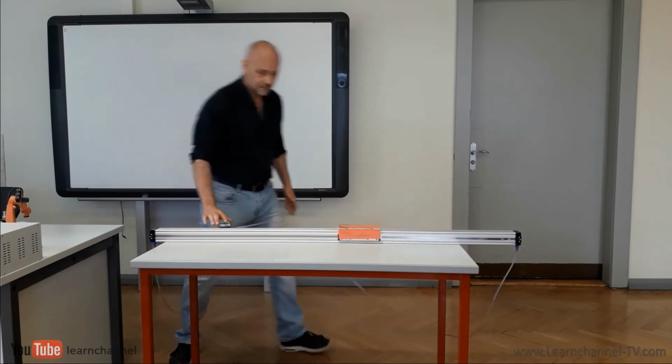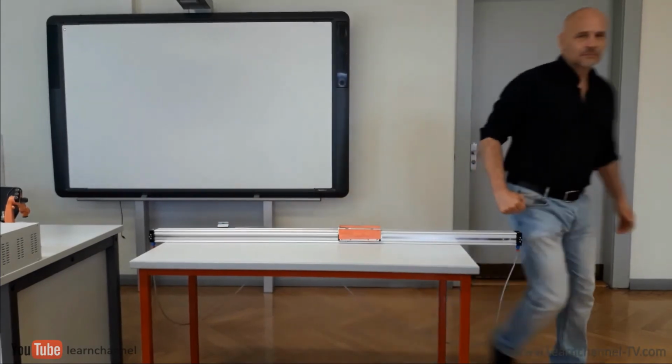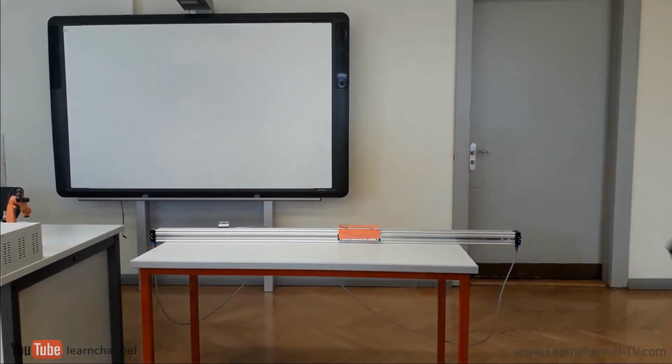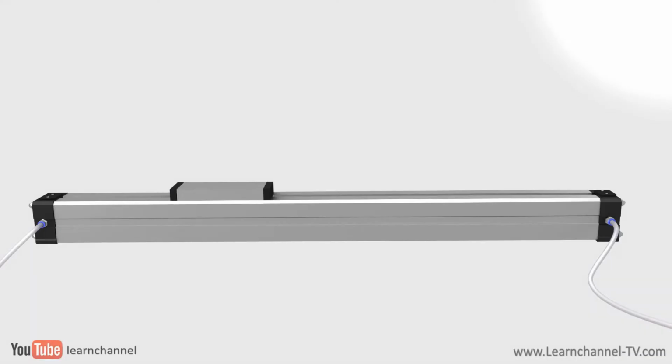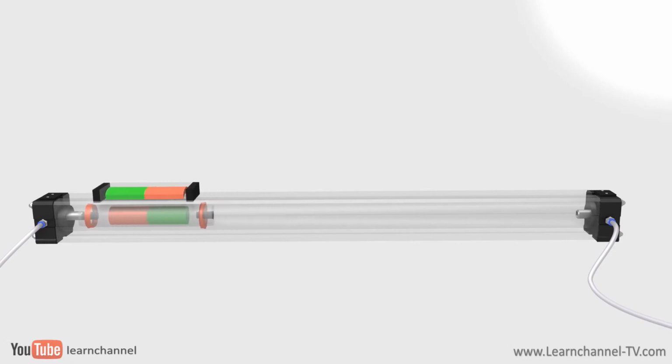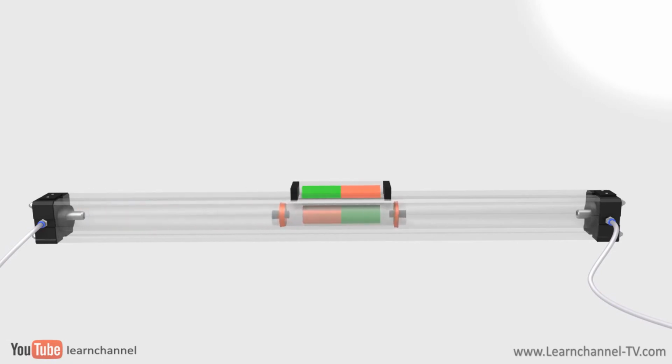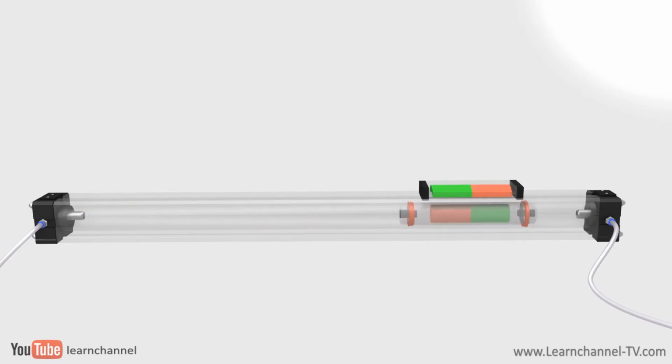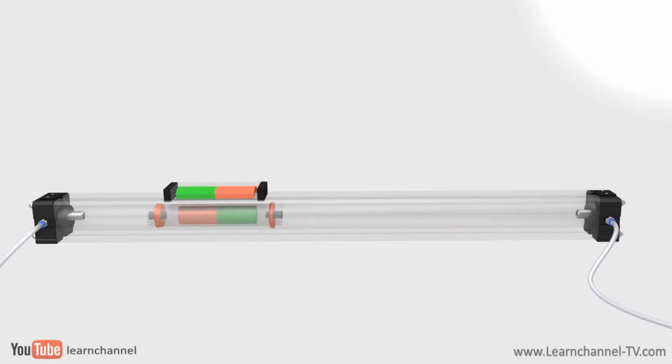Different types of rodless cylinders can be distinguished by the way the piston is connected to the carrier. One principle is the magnetic coupling. Here, the piston and slide are connected together by using permanent magnets. One magnet integrated within the slide, the other one within the piston. In this design, the piston can move in a completely enclosed thin steel pipe.